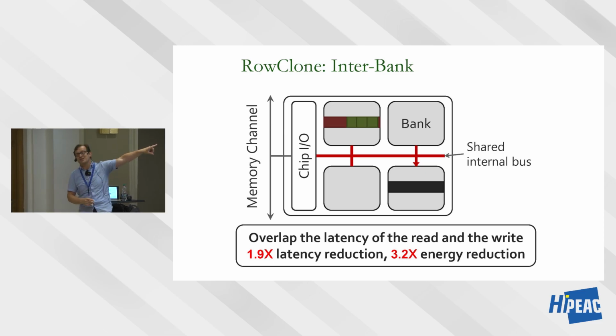Here, they're not sharing the sense amplifiers. Here you have to go through a read from an internal structure inside the DRAM and a write to another internal structure inside the DRAM. But you're not going out of the chip. You're not exercising the huge chip I/O pads.